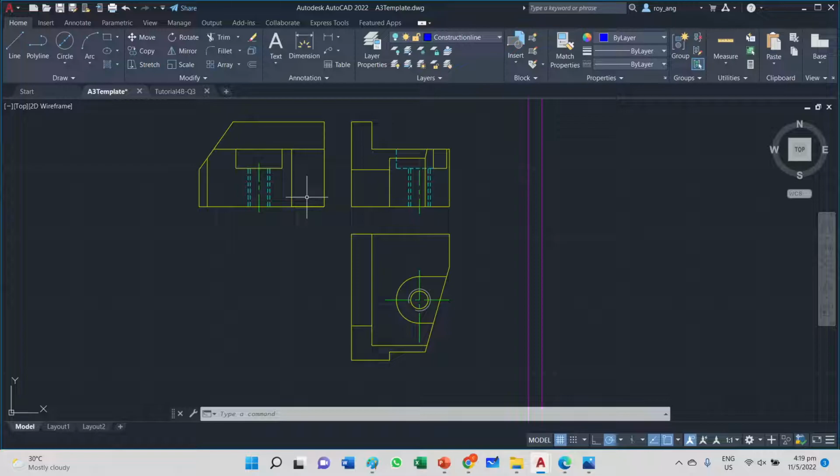You would need to stop, then progress to the next view, then stop again, progress to the next view. And once that's done, come back to it again using the mitre line, the 45-degree line, and make use of projections to find intersections that were previously not there. And then you project that point or the intersection point down and across to get the positions in either your front view or your plan view, or from your plan view you project upwards to your front view, and then you complete your drawing.